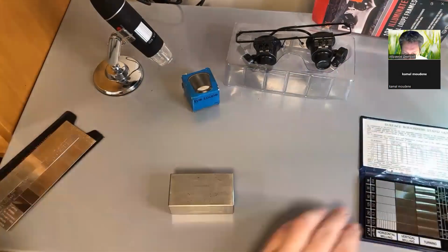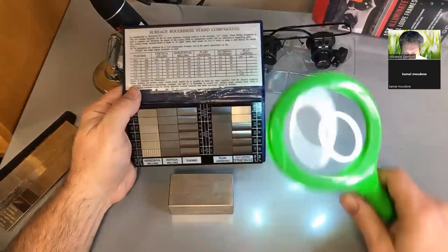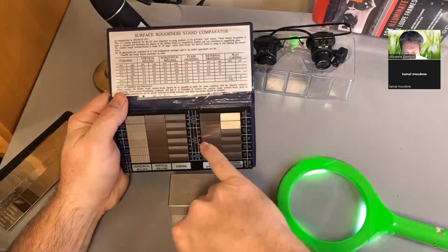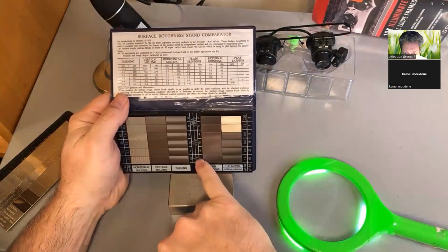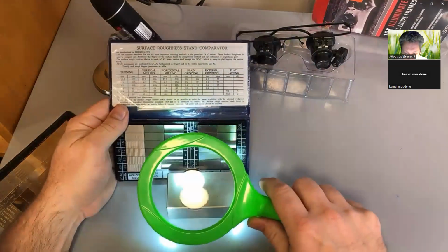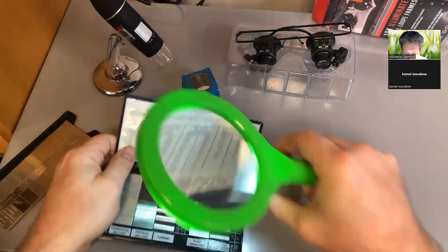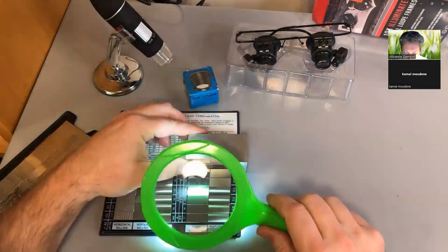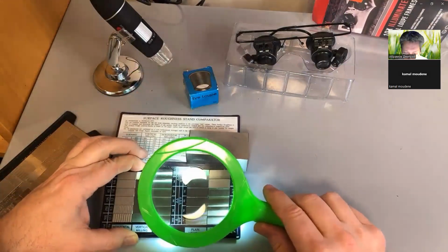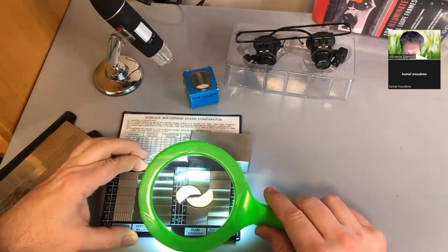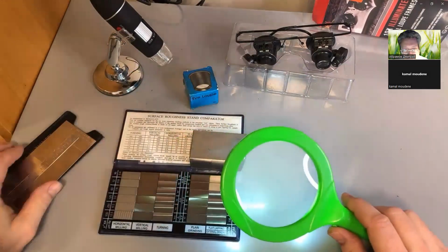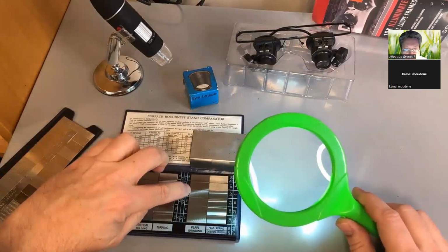So let's turn around and use this visual comparator here. And if I look here, I have a 3 and a 2 and a 4. So I got 7, 6, 5, 4, 3, 2. And I take a look here. We go this way here. I would almost say between the 4 and the 3. And it's so close it could even be a 2. So I'm going to say between this range right in here.